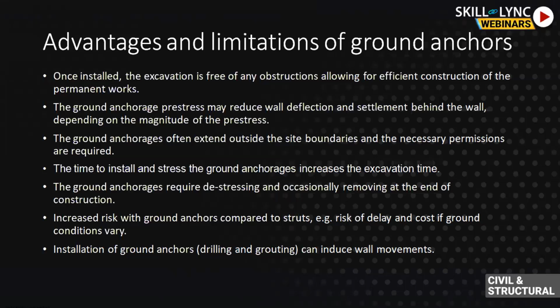After construction, the ground anchorages should be de-stressed and sometimes removed. So when it comes to ground anchors, there is delay and the cost increases compared to struts. But the only benefit of anchors is that you have free space for the construction, so it won't affect the construction. But there are some other limitations, like in many places you cannot go for ground anchors. Sometimes the drilling of ground anchors and grouting can also induce some wall movements.